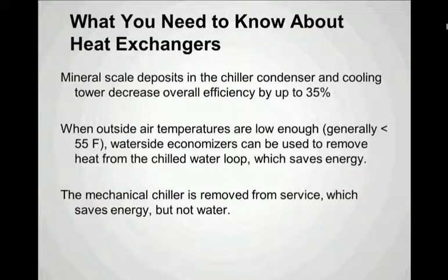If water side economizers are an option in your particular area, then when outside air temperatures are low enough, the water side economizer can be used to remove heat from the chilled water loop, which offers the opportunity to save a lot of energy. And finally, the mechanical chiller, when it's removed from service by virtue of being able to use a water side economizer, saves a lot of energy, but not necessarily water, since water is still required in the cooling tower to reject that heat to the atmosphere.